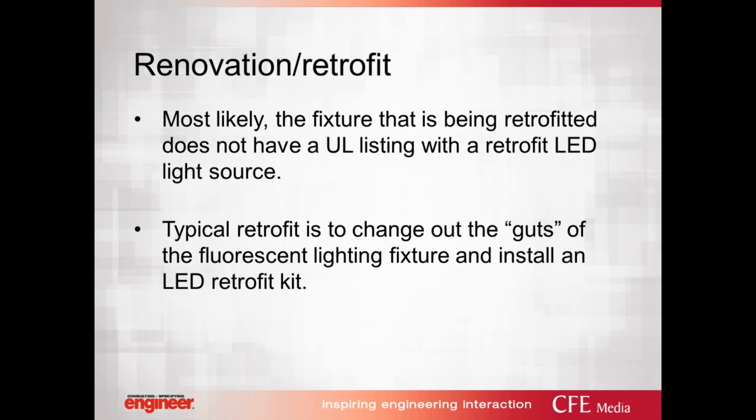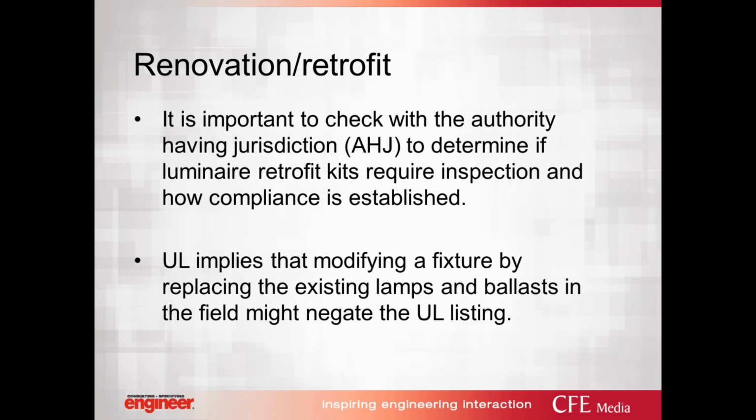There's also another type of retrofit where you actually keep the fluorescent ballast, and then you replace the fluorescent tubular T8s or T12s or whatever you have with tubular LED lamps. Now, one thing to keep in mind when you do that, since you're not replacing the ballast and the driver is still integral to the LED tubes, is that you're typically not going to realize the energy savings from using LEDs, because the ballast is still going to be drawing that same amount of power.